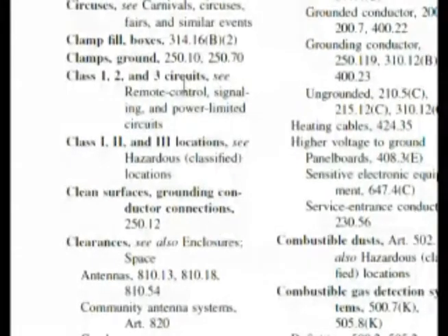I know when you've got class 1, 2, and 3, it's also similar to these hazardous classified locations. So I went straight to hazardous locations, and I thought I was taking a shortcut, and I started looking for cable types. And I was on the wildest goose chase through the index. Now in hazardous locations, you've got class, and you've got Roman numeral 1, 2, 3, and then you have our normal, actually called Hindu-Arabic numerals. That's a historical point for you, class 1, 2, and 3, or the normal way that we're used to writing them.